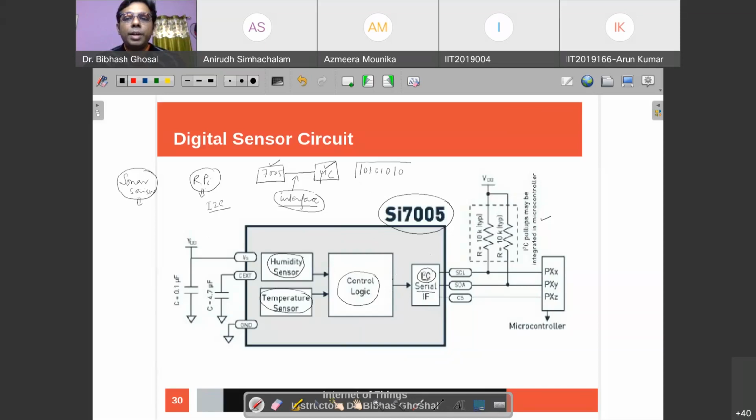So this is the 8-bit data that has to be transferred. Now, if it is transferred one by one, like this is first, then this, then this, then this, so it's a serial way of transmitting. I2C is one such protocol where you have a clock and you have a data. Only 2 pins through which it starts transferring. So there's a start, a kind of clock thing that begins or mentions that, okay, now I'm going to send the data. So it's an initiation, and then the data is sent, and then there's a stop. It's pretty simple logic. It's a very easy way of communication.